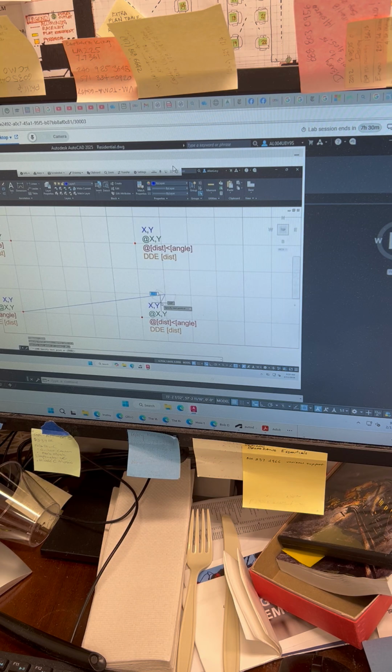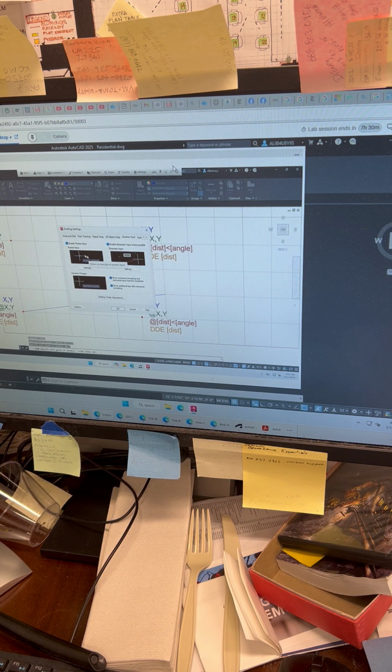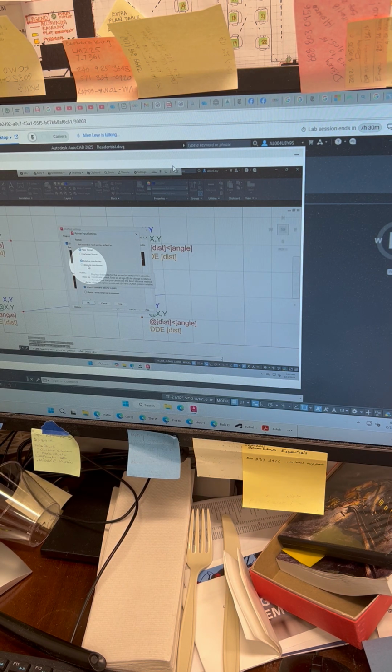All right, now, I just remembered that my dynamic input is set to relative. That's my fault. I forgot that these machines are set up this way. So what happened here is it did not allow me to use absolute coordinates. It automatically deferred to something called relative coordinates, which I'm going to get to next. Let me change that to absolute coordinates, and then we'll be able to do that again.